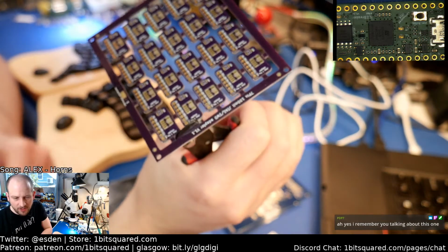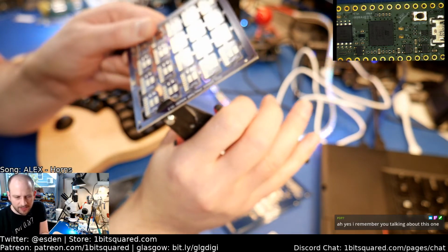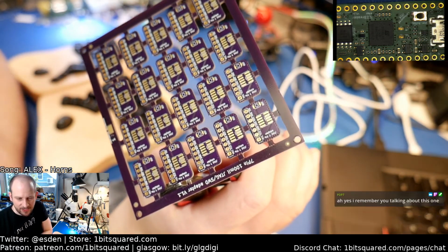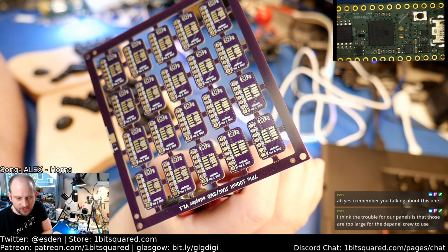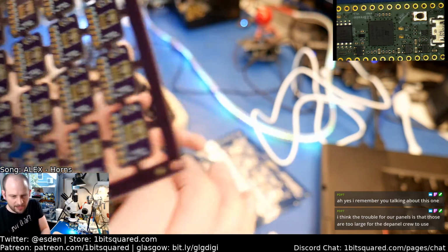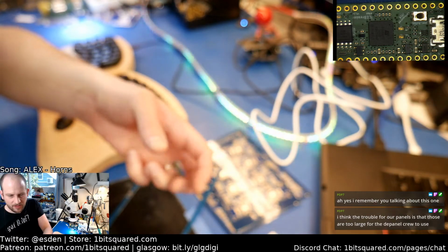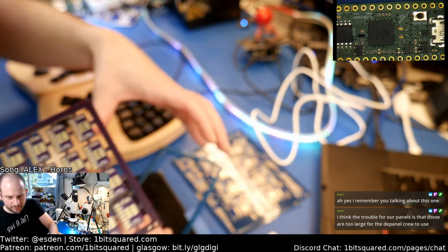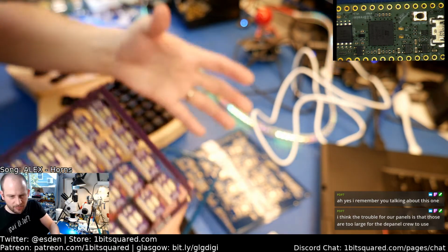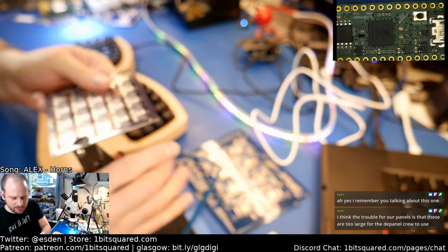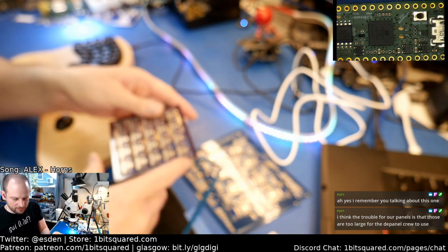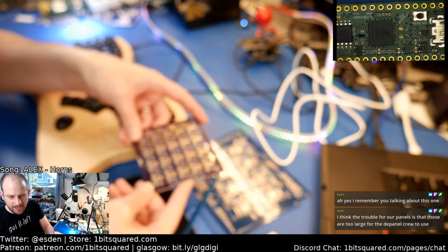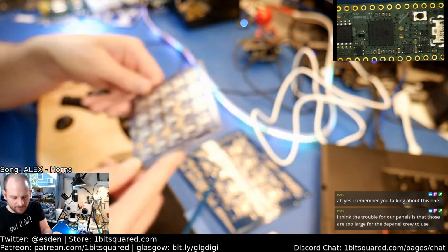There are more ways of breaking out tab and route. Some companies, I've seen that visiting Screaming Circuits, they actually took a table and put a router head from the bottom of the table with a ring that can suck the particulate away, and essentially an operator directly guides the board in the air more or less on the router itself and cuts them out.